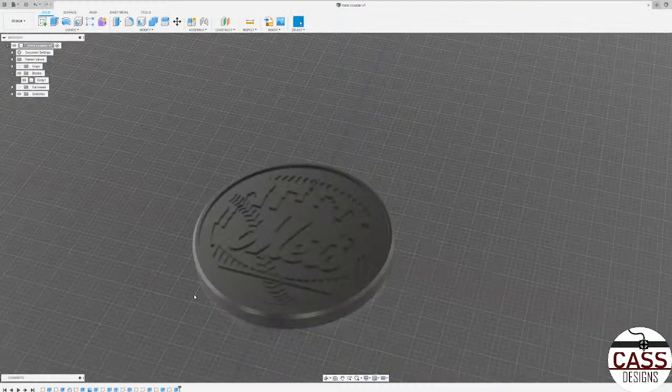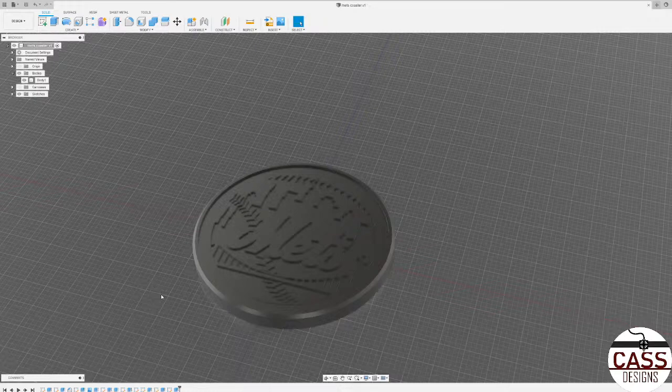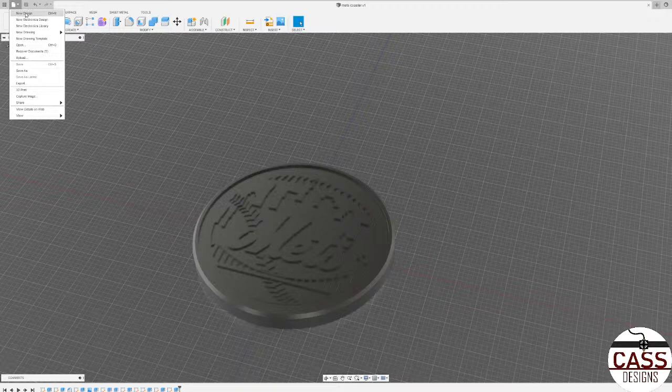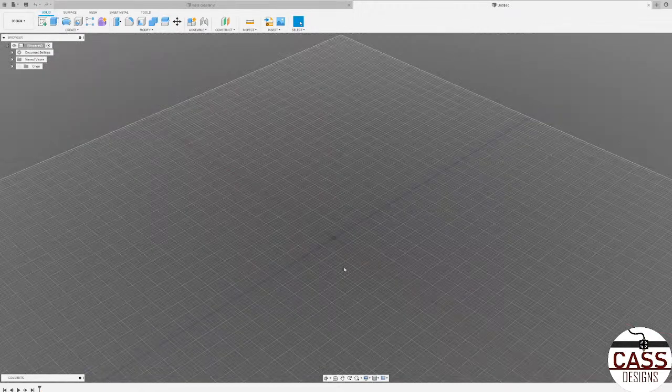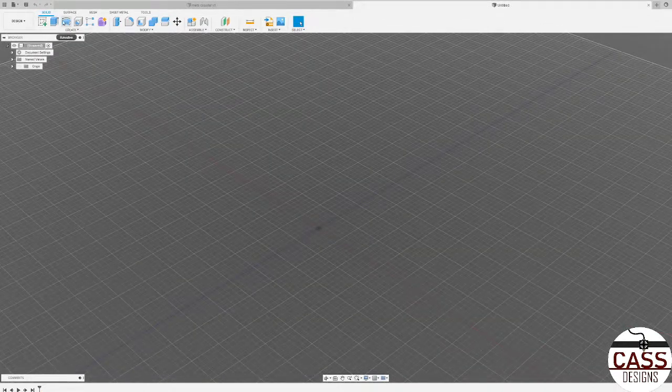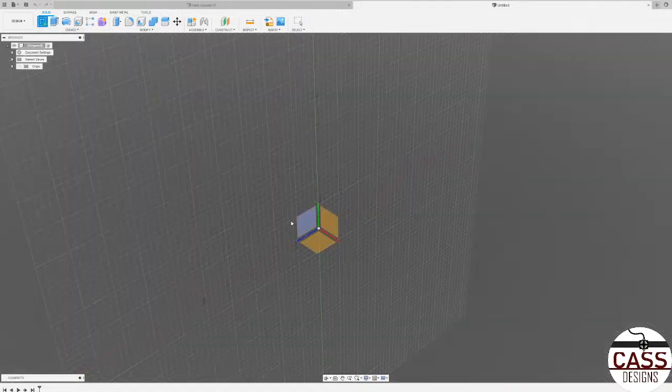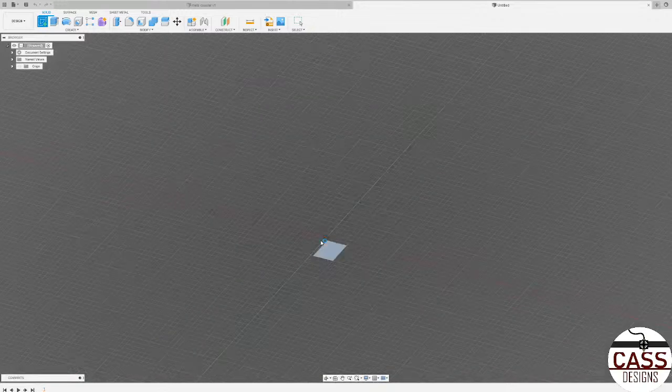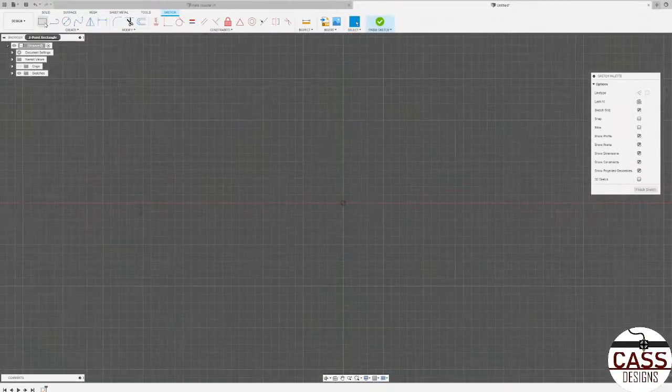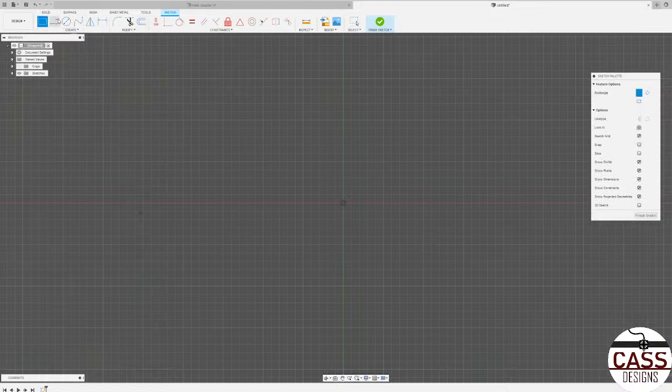So the next thing I'll do before ending the stream is just create a new design. So now we're starting from scratch again, empty canvas. And what I'm going to show you is how I create a standard keycap model, which I did in a couple videos. So we're going to start out with a rectangle up top using this bottom plane, like I talked about before. And I'm not going to use any dimensions right now because this is just a general showing for anybody that's interested.